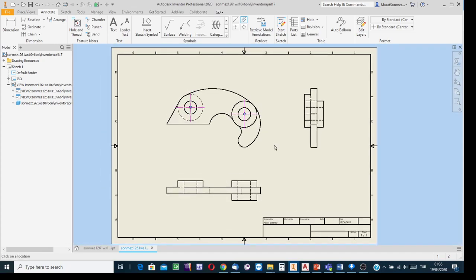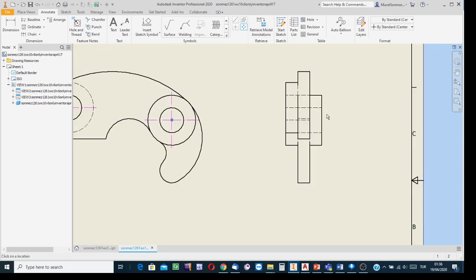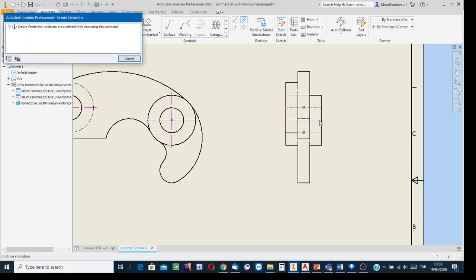After finishing this video record, I'm going to restart Windows Explorer, and then without any difficulty I can indicate the longitudinal axis here, and on the left side view as well. Longitudinal axis, click on this button, and then I see that this is the limit of the hole, it is over here, and this is the other limit, indicate, and between them we have the longitudinal axis.